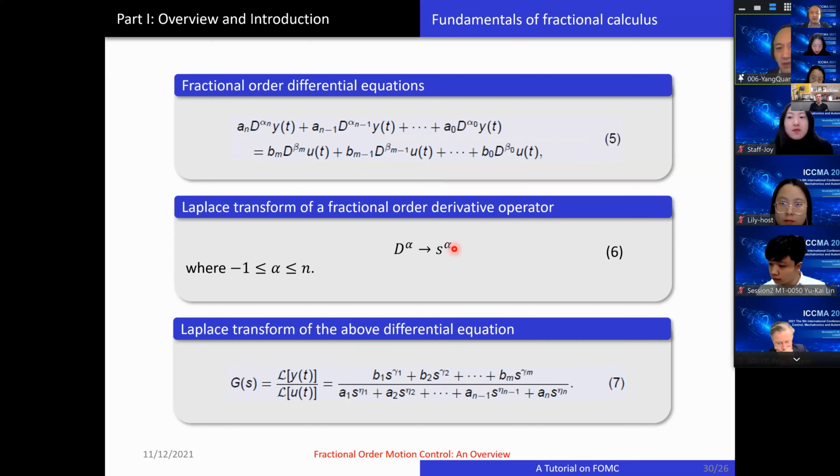So you can write a Laplace transform. Of course, we assume zero initial conditions here. Then you can write this type of general fractional order differential equation, linear time invariant. This format can be put into MATLAB by a famous MATLAB toolbox developed by Professor Xue. It's called FOTF, the fractional order transfer function tool. You use it just like the TF transfer function tool in MATLAB. You can input this model in there, then do anything you would do with a regular transfer function. It's amazingly efficient, so try it out.